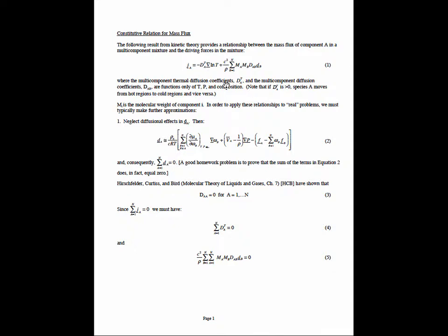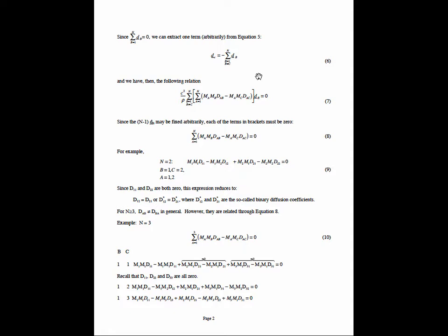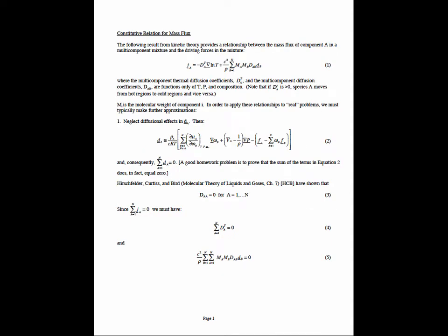And so this writes the mass flux in terms of gradients in temperature and in gradients in the so-called generalized driving force, d sub A. This generalized driving force basically gives the effect of chemical potential on the effect of concentration, pressure, and these species-specific body forces on chemical potential. Again, by far the most important one will be the one involving the effect of concentration on chemical potential.